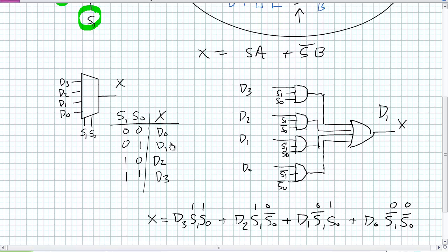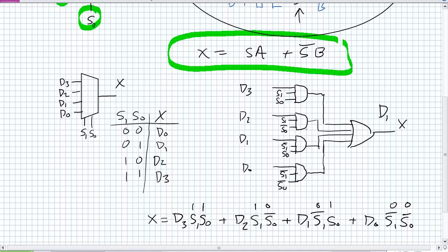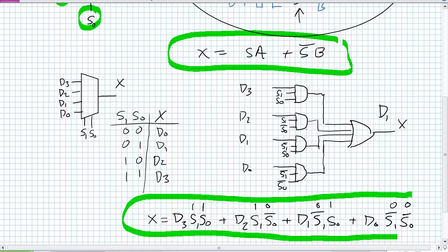And what's really neat about the multiplexers and demultiplexer lectures, and kind of supporting exactly what we just went over in the adder lectures, we can do this in a structural approach. Okay, I know we just came up with an SOP expression for a 2-to-1 and an SOP expression for a 4-to-1. What I can do is expand these things.